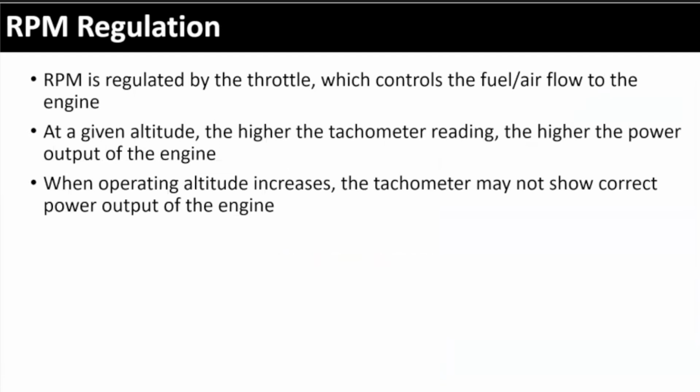Increases what? RPM. It does, but what does it increase really? Not just air. Fuel air mixture, right. It increases the amount of fuel air mixture, which creates more power, makes the engine go faster, increases the RPMs, right? So the throttle is controlling the fuel air mixture or the fuel air flow. Okay. Right.